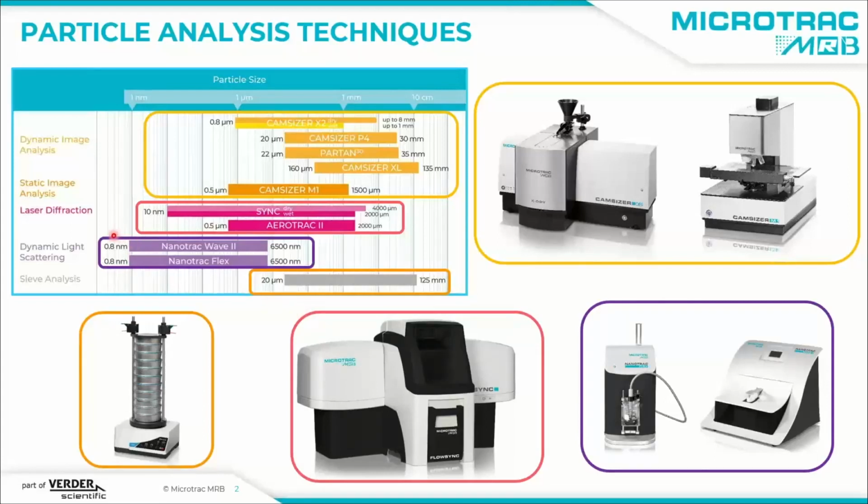Finally, here at Microtrack, we have a technology which is called dynamic light scattering. Dynamic light scattering is a method that works very well for nanoparticles. So everything that is in the lower nanometer range, this is where you would use dynamic light scattering. For metal powders, this is not what you would like to use. It can only measure wet, so it's not suitable for metal powders, but very good for nanoparticles.